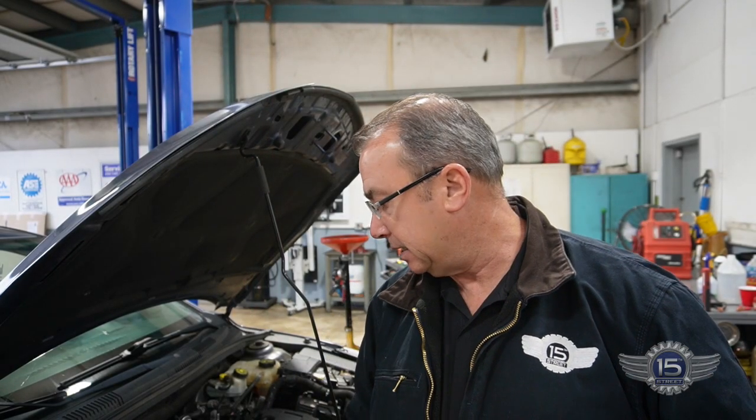So I tried to hook up both scanners at the same time. I've got a T adapter for the ALDL. As soon as I command that evap closed, it kicks the other scanner off. So there's something in the communication there that it doesn't like to do bidirectional while the other scanner's reading. Otherwise, we could monitor the trims at the same time that we're commanding the evap closed with a different scanner. You can't monitor trims and turn the evap off on the same screen. So I had two scanners hooked up, but it won't work.